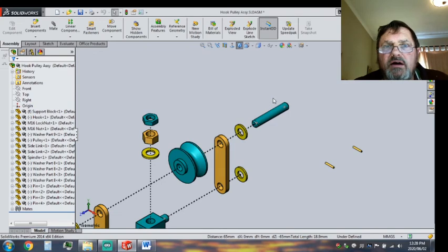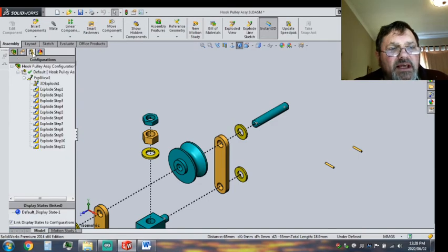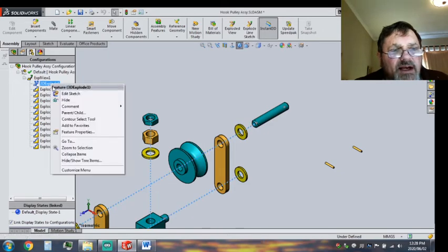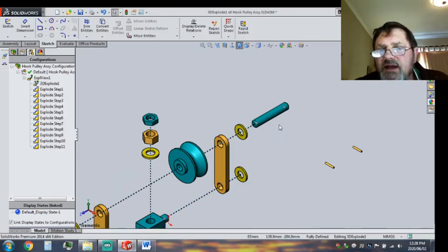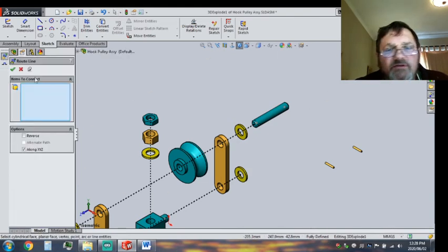So now I want to add more root lines. I have to open my root line sketch to add more root lines. Once again, the root line sketch is hidden here. It's a normal 3D sketch, so I can just right click, edit the sketch. Now I'm in the root line sketch. Now I can take that fellow. If you don't go edit and you start a new one, you could end up with a lot of sketches and then it's going to have unpredictable results.